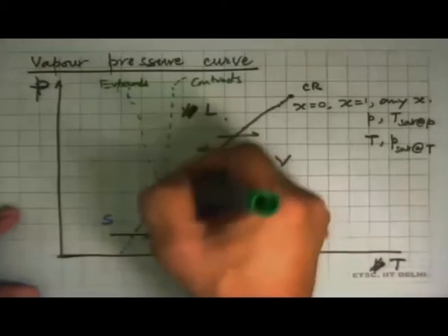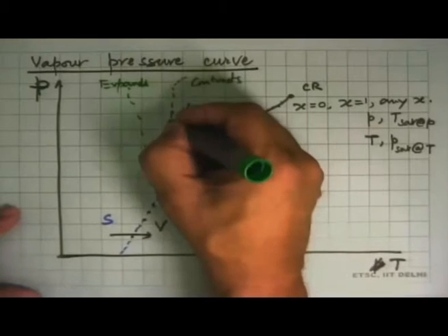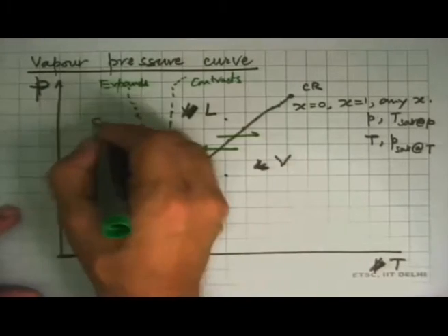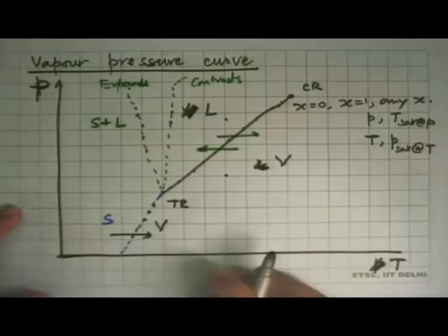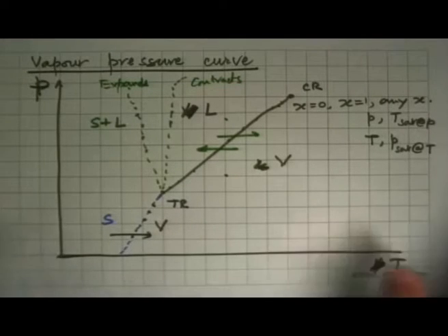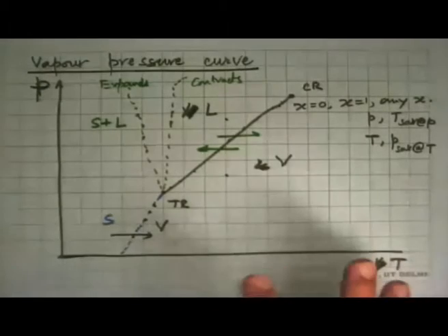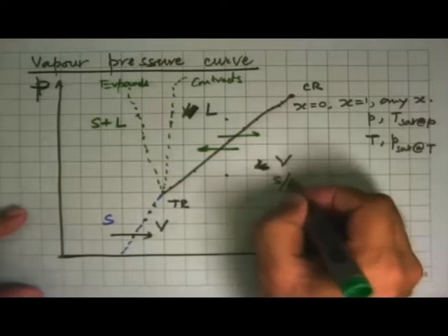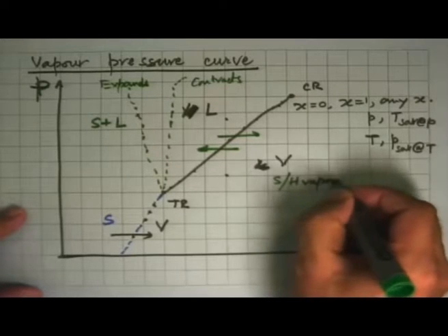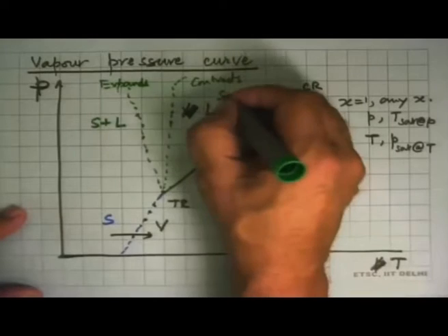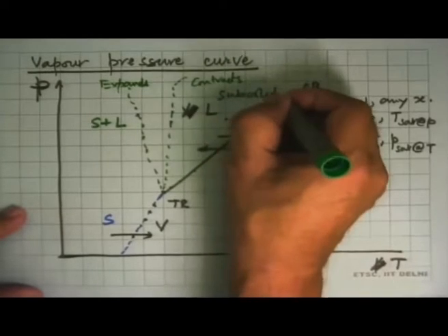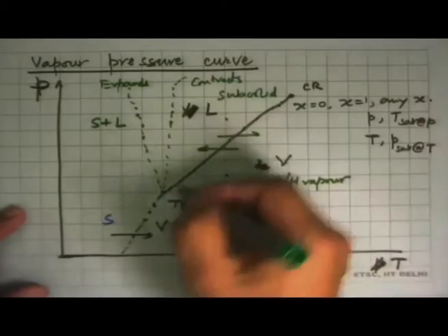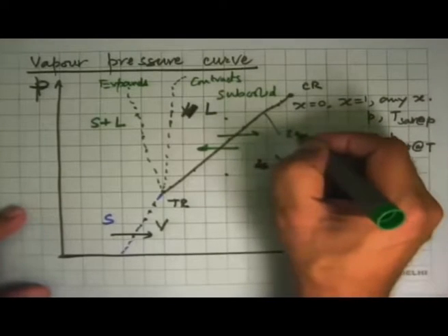So these lines represent the lines where you have equilibrium between a solid and a liquid state. Okay, so this tells us in a nutshell all types of states that are possible, and this vapor means this is superheated vapor. This liquid means it is a subcooled liquid, and just solid in this. And this line is saturated states.